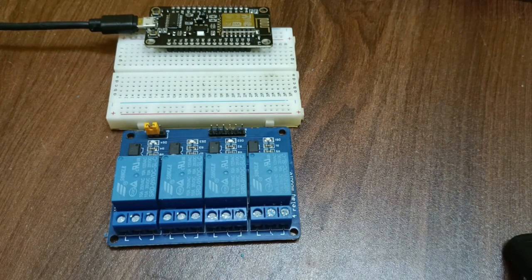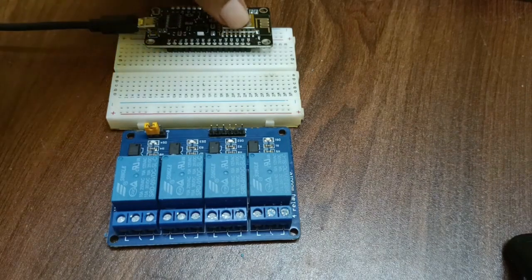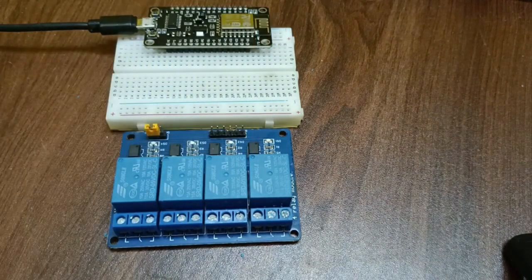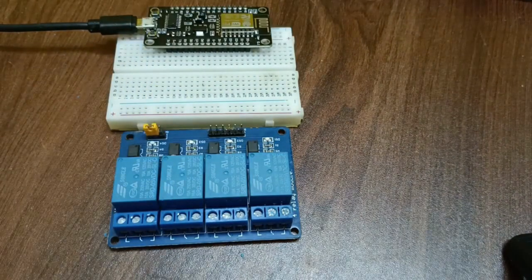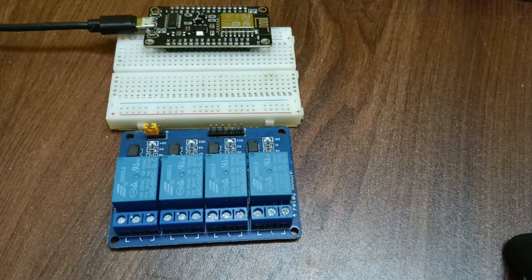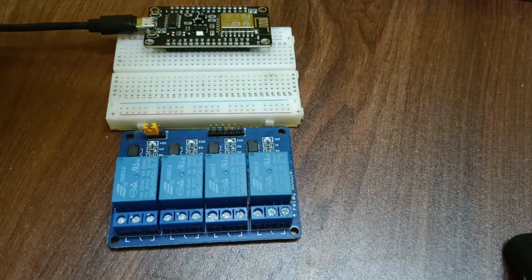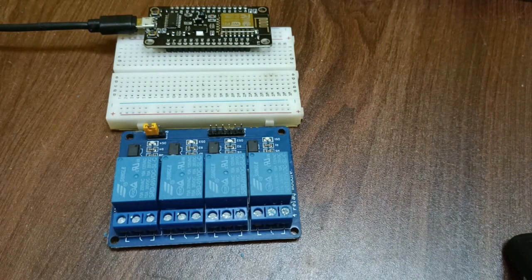and all the home appliances we can see are AC appliances, but our ESP8266 can't deal with the AC. So here we are using the relay circuit. Okay, so we already saw in the previous project how to control the AC appliances using the Arduino. This circuit is gonna be very much the same, or I would say similar. Then we will quickly jump on to the Arduino IoT cloud to set up the cloud to control turning on and turning off your appliances from the Arduino IoT cloud dashboard.